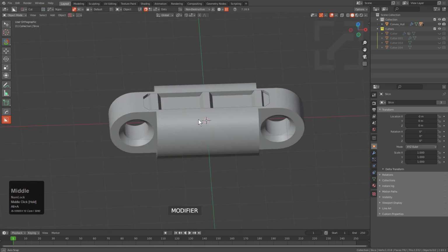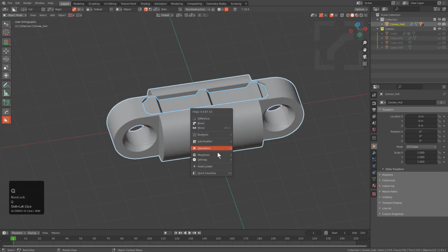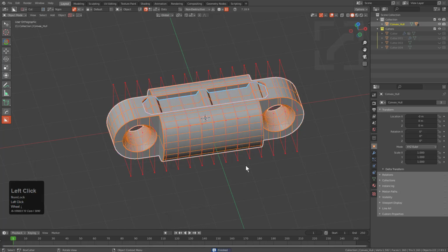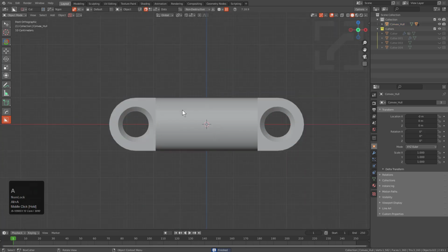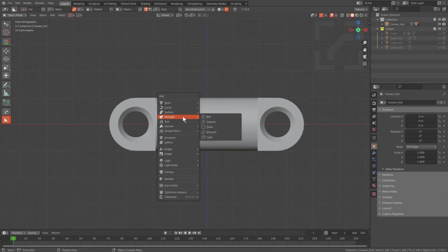So with this shape, if we wanted to deform it along a curve, all we have to do is just select it, mesh tools, dice, and we could press S to smart apply, which will just apply everything, and then we can add some loops in. So that's it. That's pretty much all it takes in order to perform a dice on any series of objects. Well, objects, not empties or curves or anything like that.